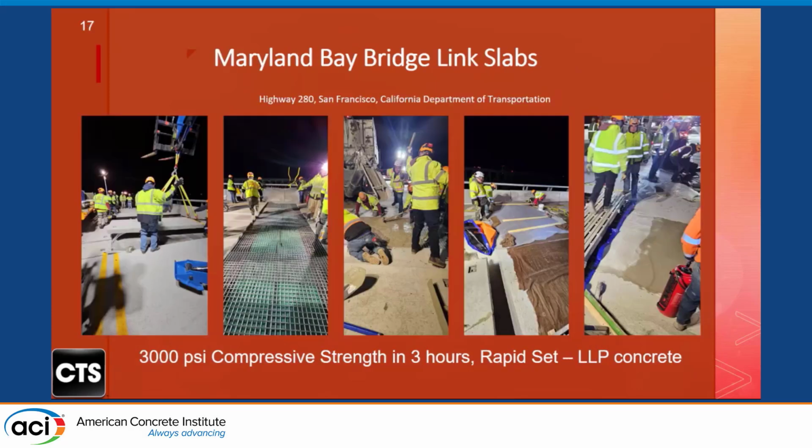I took these pictures last week or 10 days ago, not that far from here, Maryland Bay Bridge. This is a project where they are rebuilding the entire bridge sections, and they are building the link slabs using BCSA cement. They get the bridge around 9 p.m. and they need to open it at 4 a.m. Heavily reinforced, and it performs.